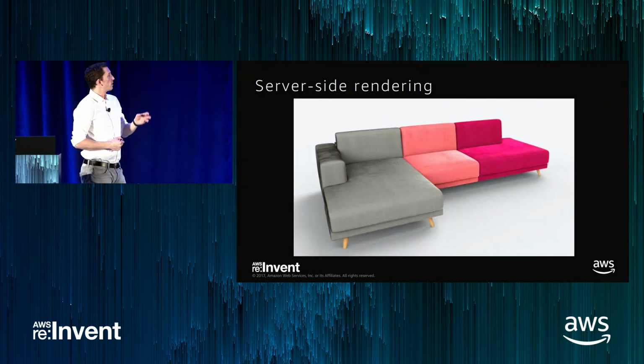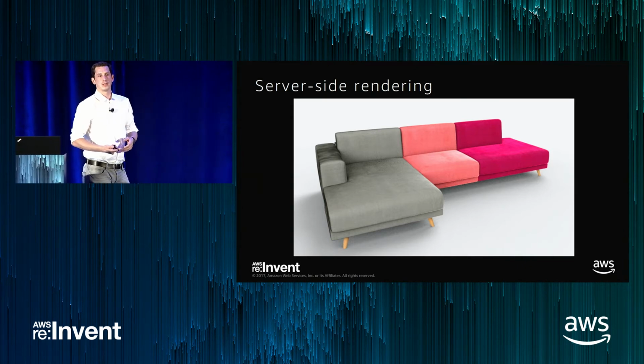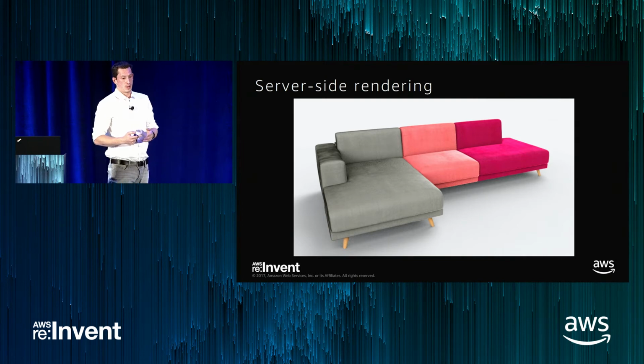So if you render exactly the same image with the same scene, the same 3D geometries, textures, and materials, this is what you get from a server-side renderer. It looks much better, especially for fabrics. They are extremely difficult to represent with WebGL. There are a few other situations, like when you have very glossy, highly reflective surfaces, where you can use WebGL and it's going to look okay. But if you have fabrics where you have different colors and shadings depending on your light settings, that's something that you will probably not be able to manage with WebGL.